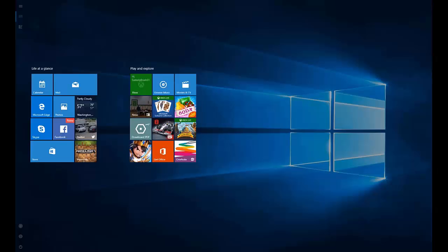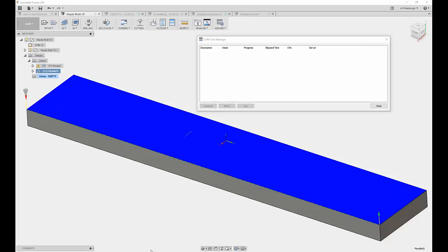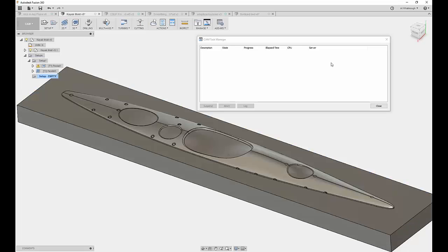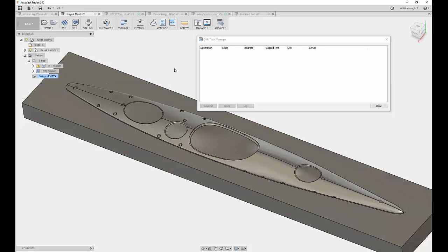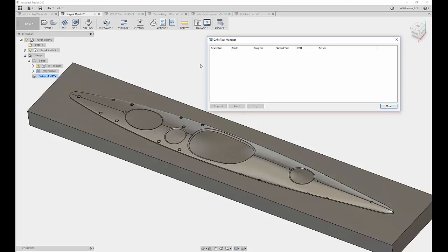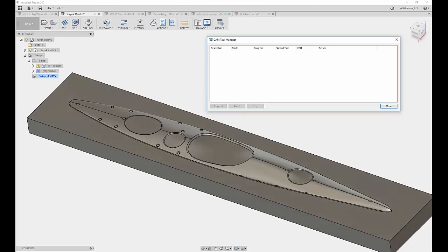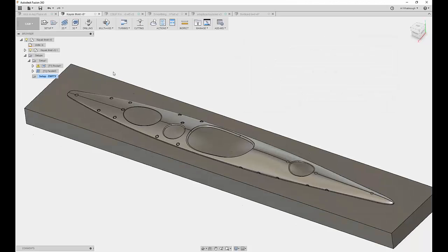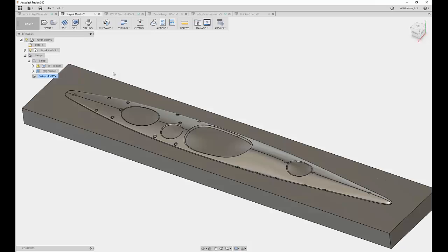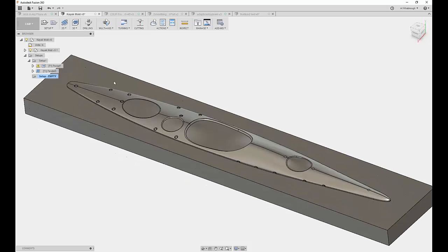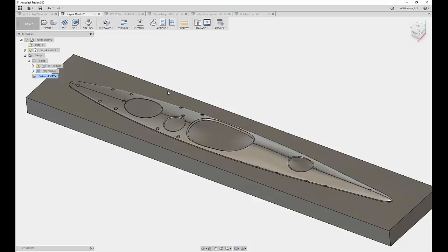So let's start by taking a look at the multi-threaded side of the toolpath. At the same time, maybe we'll look at what the best tool for the job is. I often think adaptive clearing is sometimes overprescribed, so it's going to sound funny as a product manager to maybe not talk about one of the very strong toolpaths in our bag. But here we're looking at a mold of a kayak. If anybody's curious how a roto mold works, you actually machine a positive and then they fiberglass over top of that positive, and that creates the negative for the mold. So we're cutting this out of wood, and it's very likely that adaptive clearing isn't actually the best for this.